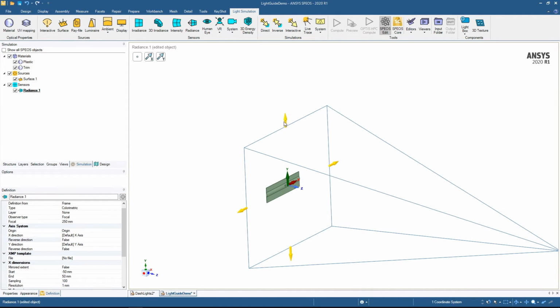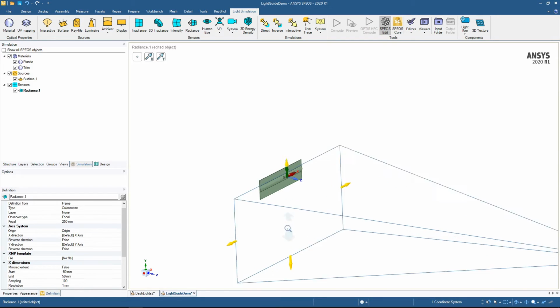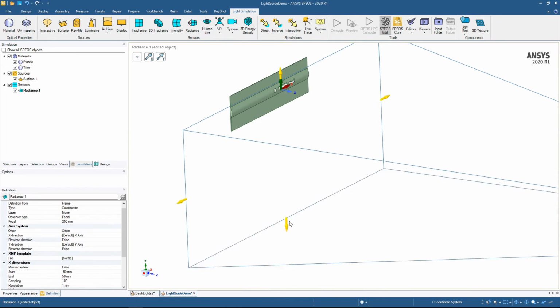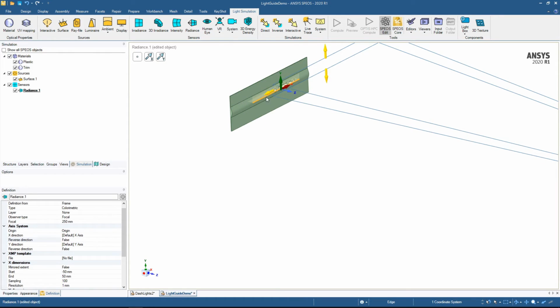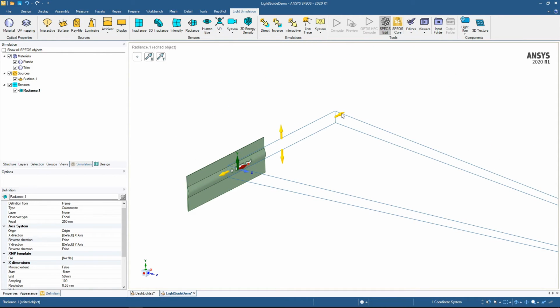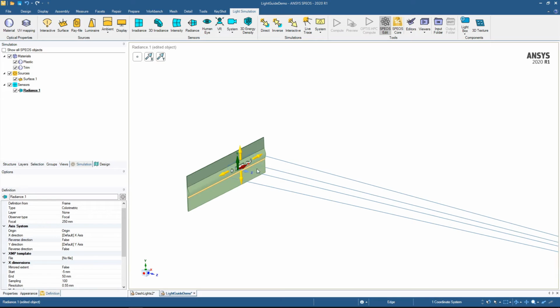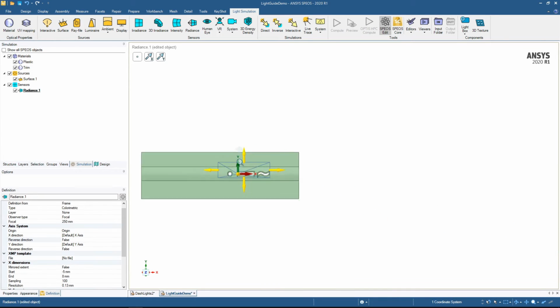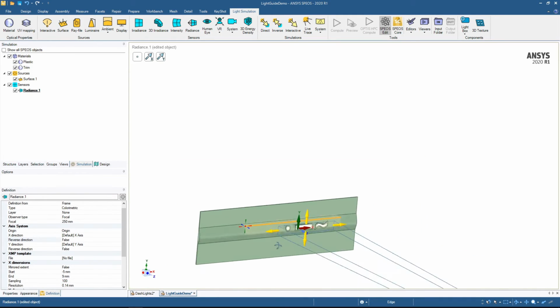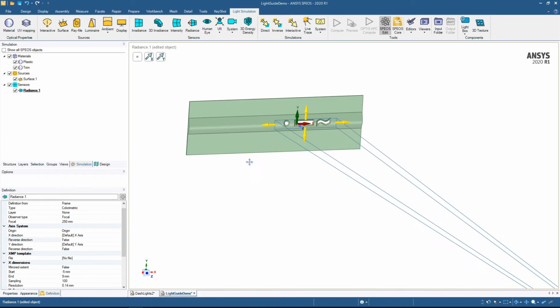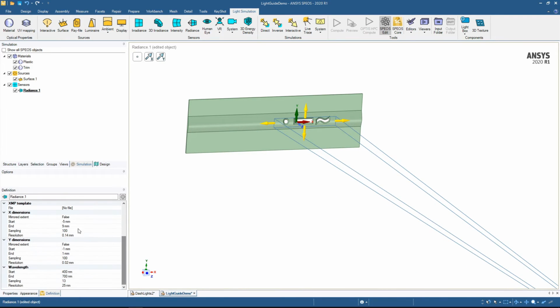And I'm going to shrink it also, just to make sure that we're not trying to capture rays from too large of an area. As you can see, I've just brought down the range that the sensor is effective on. Let's have a look to see how that looks. Maybe I'll want to move things over a bit. There we go. Okay, I think this is good. All right, so the range of our sensor is defined.